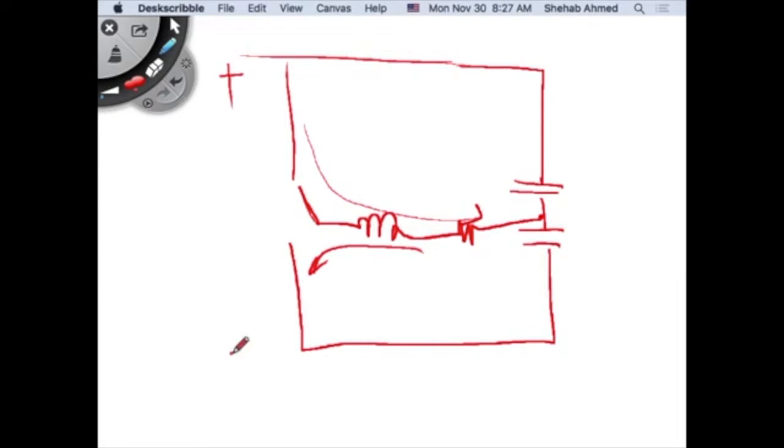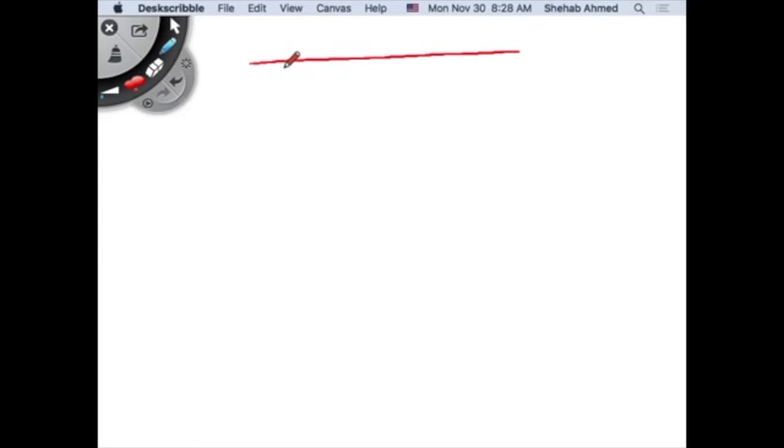This is plus minus VDC. So when you are in the dead time, none of these two switches are connected, but you will have current. Let me draw them with the diodes and switches, because then you can see that the current will have to flow through the diodes. When the switches are both off, the current will have to flow somewhere. So where is it going to flow? Let's draw the switches and diodes together. It would be easier to see.